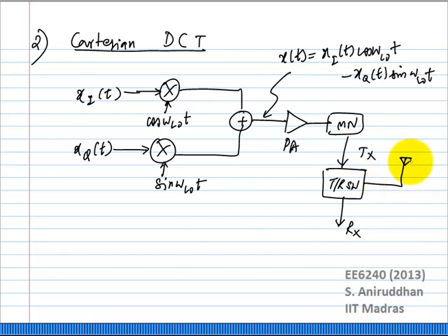The TR switch basically connects the antenna to the transmitter during transmission, and during reception it connects the antenna to the receiver. So this is one possibility. How does this realize? It's very easy, right? Using a switch. Of course it may not be a MOSFET switch. If you want a really high quality low loss switch, it could be maybe a HEMT switch or an HBT switch.